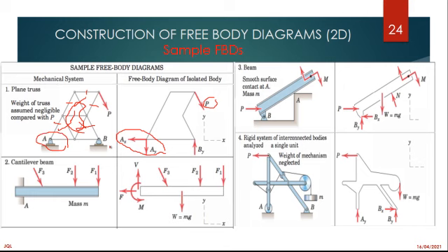You go to a cantilever beam, that is number 2. You have force 1, force 2, force 3. When I look at this reaction, I know that that is a fixed connection. I need the vertical reaction, the horizontal reaction, and the moment.